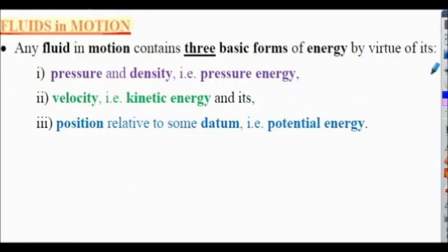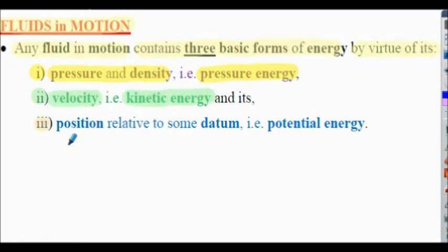Fluids in motion. Any fluid in motion contains three basic forms of energy by virtue of its 1. Pressure and density, this is termed pressure energy, 2. Velocity, this is termed kinetic energy, and 3. Its position relative to a defined datum, that's termed potential energy.